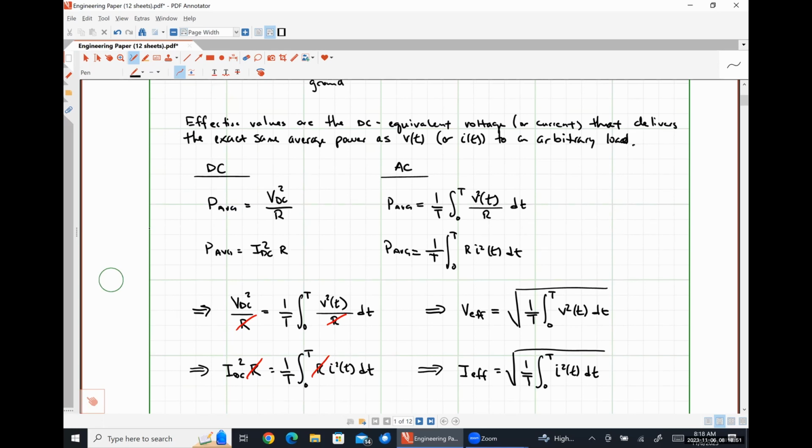And we use that to let us know that we are dealing with effective values, because the mathematical operations involved in calculating the effective value is we take the square root of the arithmetic mean, that's just a fancy word for average, of the square of our function. So we're literally doing the root mean square of the voltage in order to get the RMS value or the effective value of that voltage. Okay. So that's what RMS means.